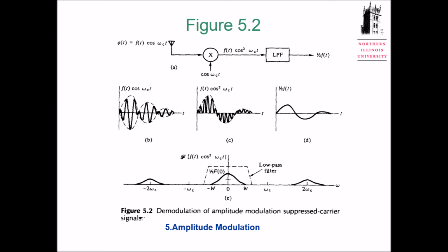Okay, then we are going to talk about how we can get the phase. How do you know the right phase to lock onto? Because if you pick the wrong one, aren't you going to get the negative of the signal? Like cosine of pi. Yeah, if the phase angle is pi, you'll get negative. So how do you tell which one is the right phase to lock onto? Let's talk about the method of getting the phase first.